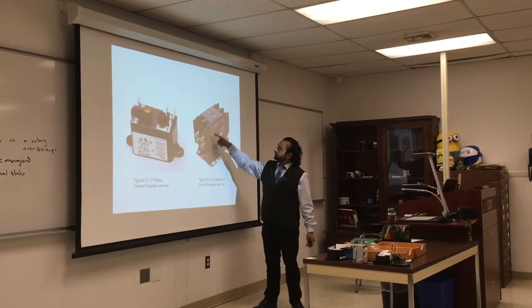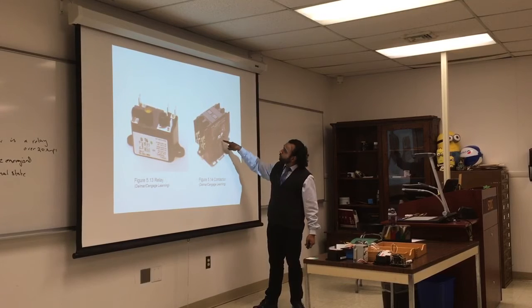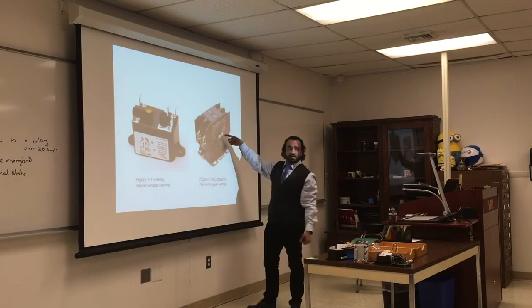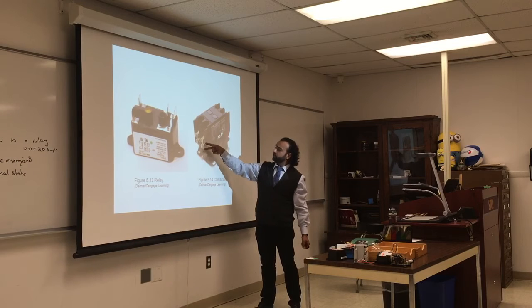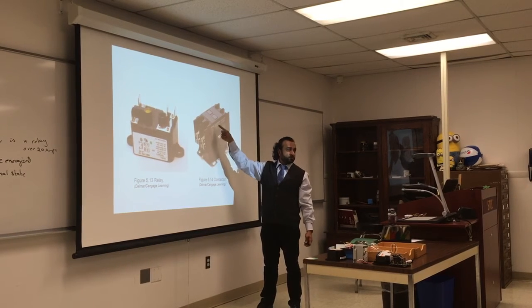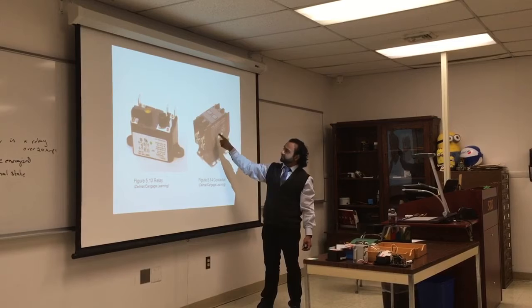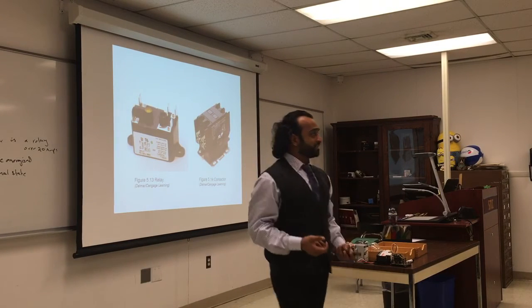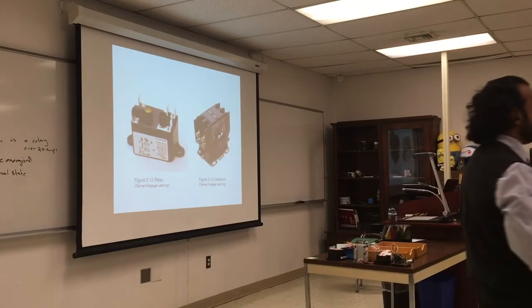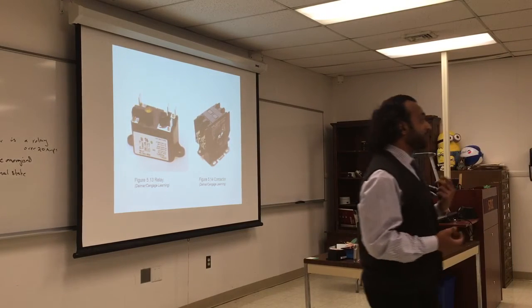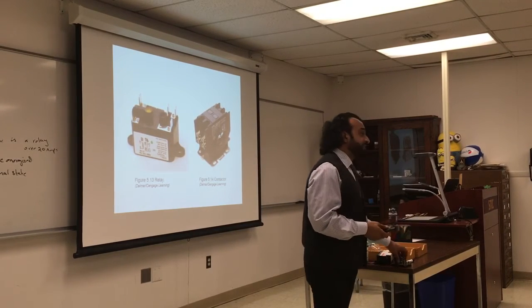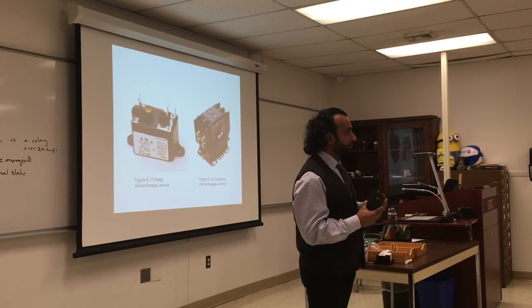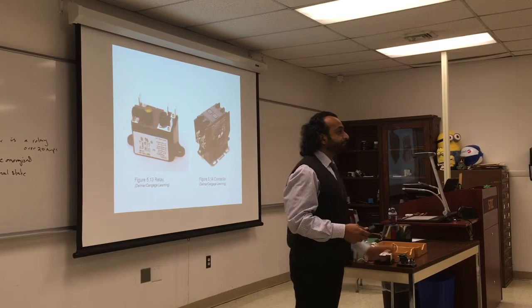And we did test the terminals. So you energize it from these two sides, it gets energized, and when it's de-energized, it will either open or close some of these connections. And we did test it for continuity. Contactors are a little bit expensive because they carry a lot of voltage. And you have seen how sensitive those contacts are. If they get dirty or get something stuck in them, they will not connect voltage.